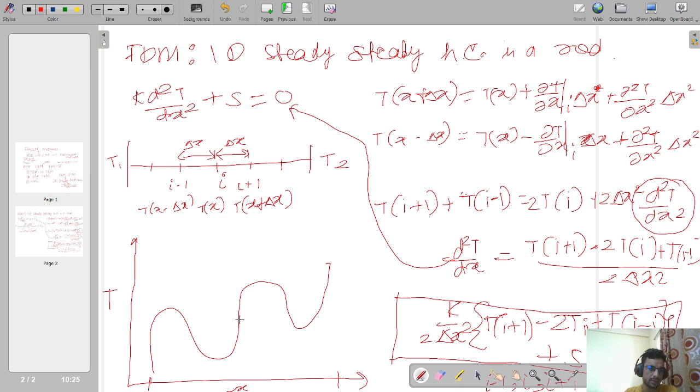The basic difference between the finite element method and finite difference can be totally understood from the name: E for element, D for difference. If we consider any two points, let's say here, in the finite difference method we do not care about the profile between the two points. We just consider these as two discrete points, nothing else. But in the finite element method, the profile is important.